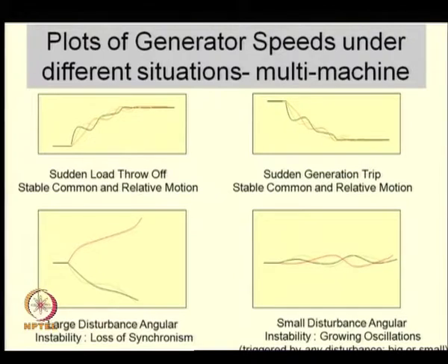Of course, generator trip is something which you have to be careful while doing, because if you suddenly trip a fully loaded generator to prevent an over frequency, it gives a big shock to the mechanical elements of your system. That is the turbine generator system, the turbines mainly. So, generation trip is not often talked in the same breath as load tripping. Load tripping is somewhat more benign compared to tripping a fully loaded generator.